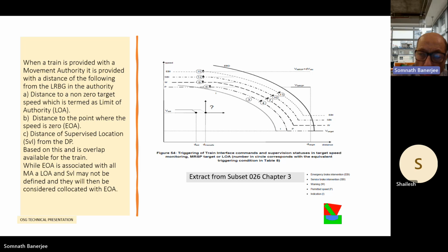That is, a train always monitors the target point to which it will be allowed to travel. However, that is not sufficient, because a train may be traveling at a speed higher than what will allow a comfortable operation of the train, and also allow it to be properly brought to a stop before an actual hazard happens.